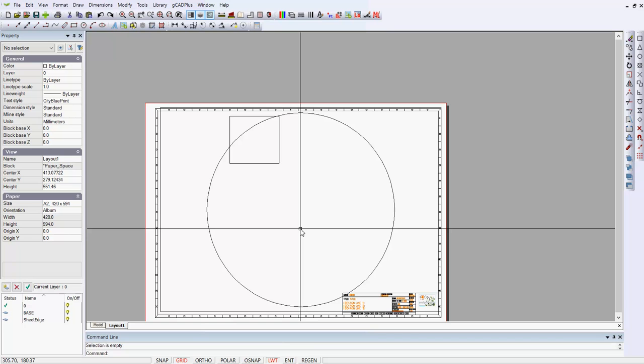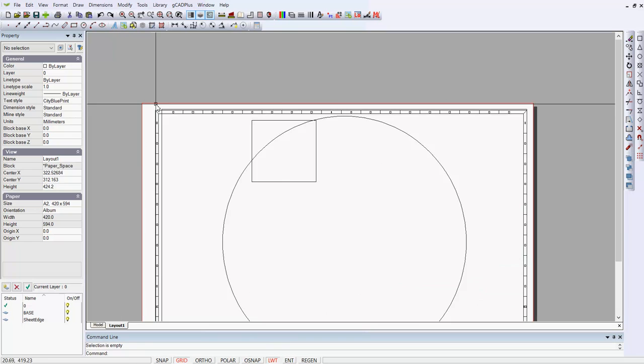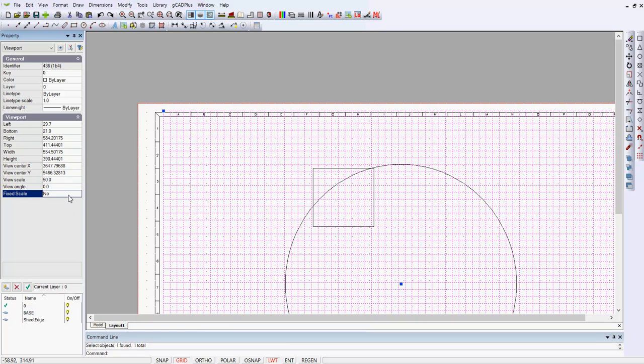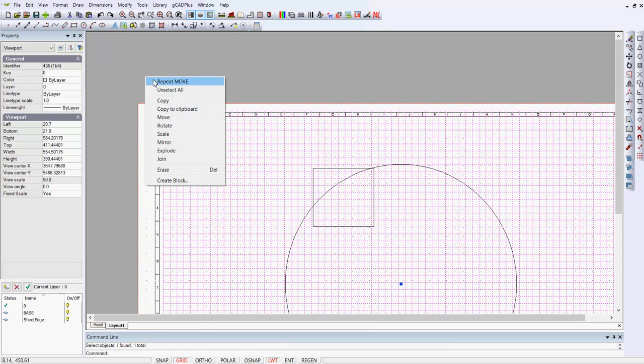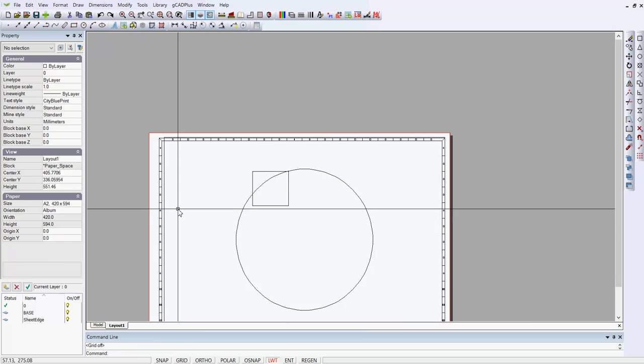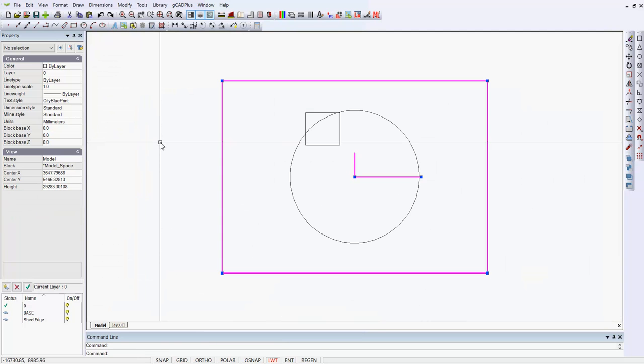So can you see that from now on, whenever we want an A2 drawing sheet, we can just navigate to the library, to the details, and then pop it in. You may have learnt that it's very useful. Pick the floating viewport. You could set a view scale at that point. Let's change the scale. Imagine we're working at 1 to 50, and we'll make it a fixed scale.